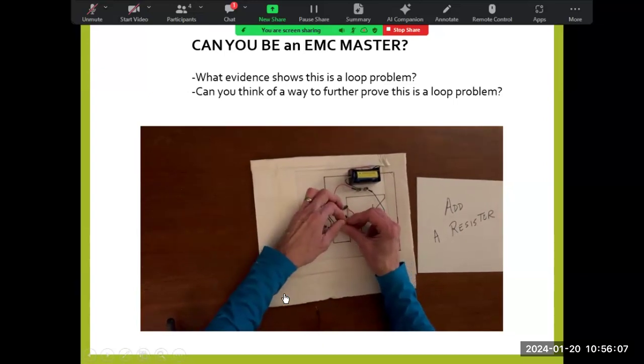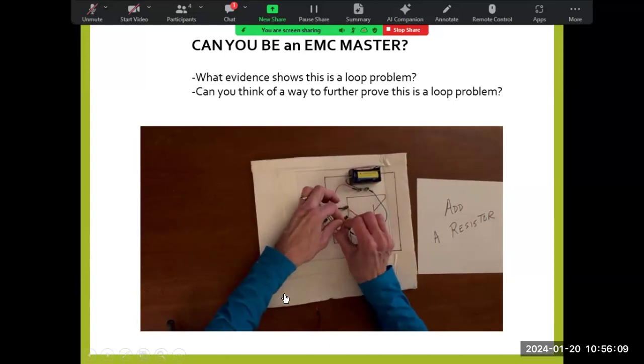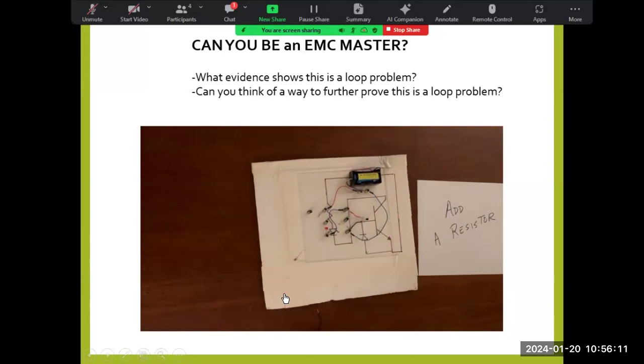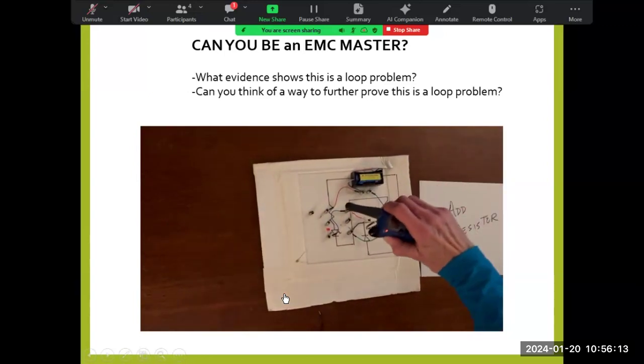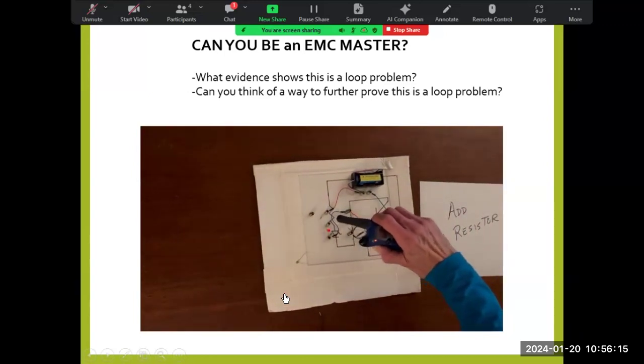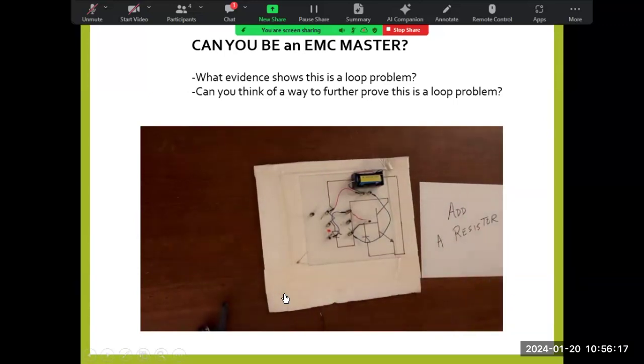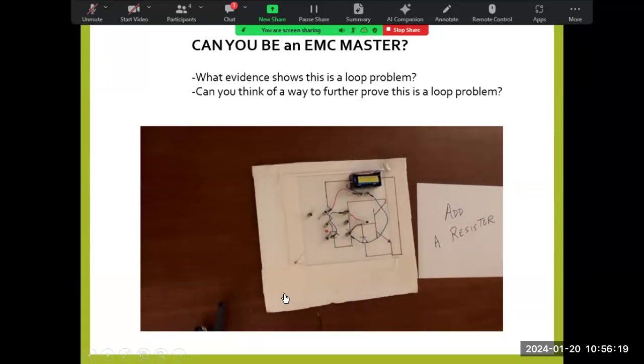There's another way to fix this circuit, which would also work. I'll tell you in a second. So the resistor worked great, right? You have to get way down there. You could also change to a different diode. This diode, it's a signal diode, has very low forward bias voltage, probably 0.3 volts or something. If you have one that's 0.7, it would probably fix it also.